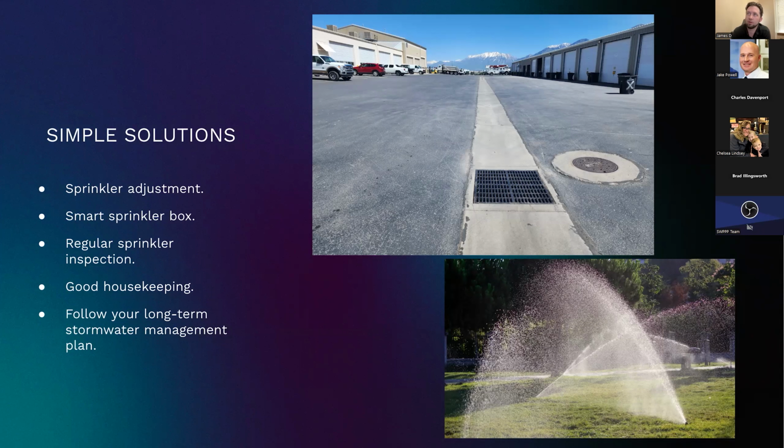So if you water for, let's say, 1 hour, the sprinkler box, if you turn it on a certain mode, can turn the water on one of your systems for 15-20 minutes and shut it off. And it lets that water open up the pores in the ground, per se. And then half an hour, 40 minutes later, it turns it back on for another 20 minutes. And that water can really get into your soil. So instead of watering for an hour, you're watering for 40 minutes.